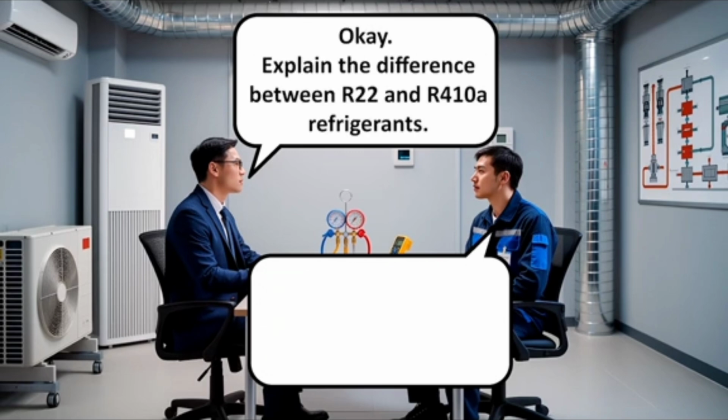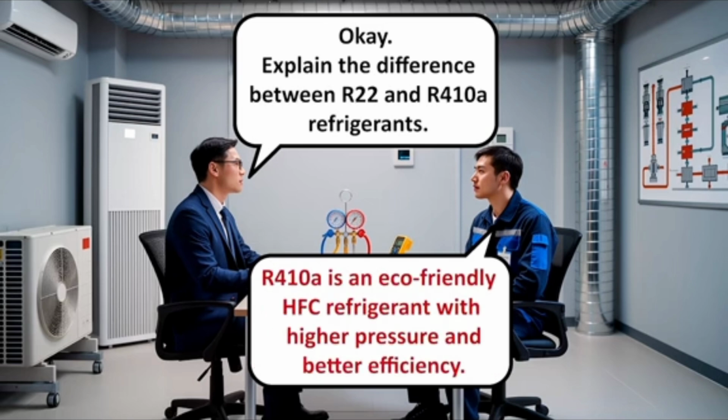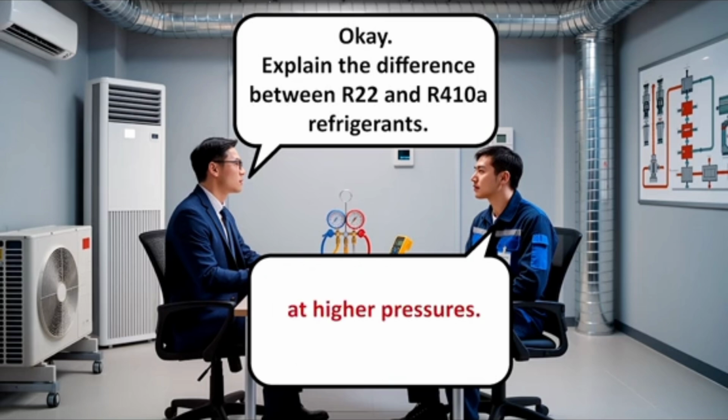Okay, explain the difference between R22 and R410A refrigerants. R22 is an older HCFC refrigerant that is being phased out because it damages the ozone layer. R410A is an eco-friendly HFC refrigerant with higher pressure and better efficiency. And yes, sir, the gauges, pipes, and equipment are different because R410A operates at higher pressures.